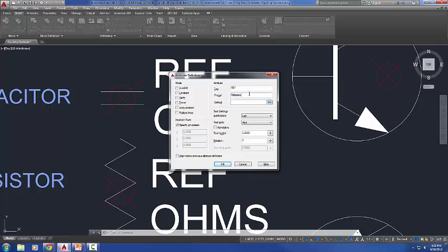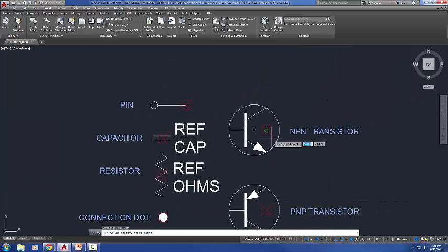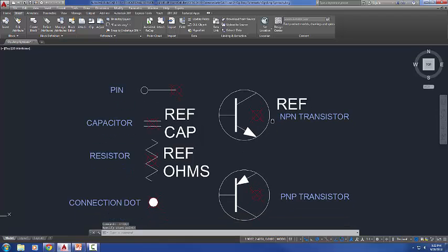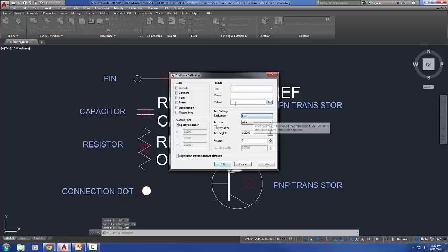I'm going to undo that real quick, and I'm going to do it again with the UCS follow turned off, just so you can see what will happen. So here's a 3-point UCS: origin, positive X, and positive Y. If I don't have my UCS follow on, my UCS did change. You can see where the positive X and positive Y are now, but my east elevation didn't flip. The screen didn't flip to show me the east elevation straight up.